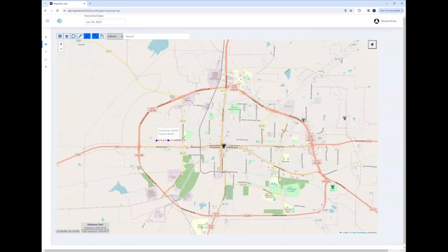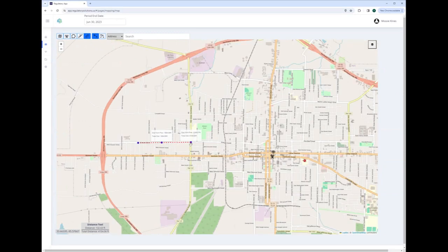So if we click another point, now we can zoom in a little bit. Now we have the total distance is 1854 to this point, and then to our second point, we can see that the total distance is 4154.06, and its distance from the previous. So it just keeps going. As you click points on the map, it's just going to keep adding these. And then down there at the bottom, as we get closer to the bottom left, you can see it's telling you your total distance and then the current distance of the segment that you're drawing.